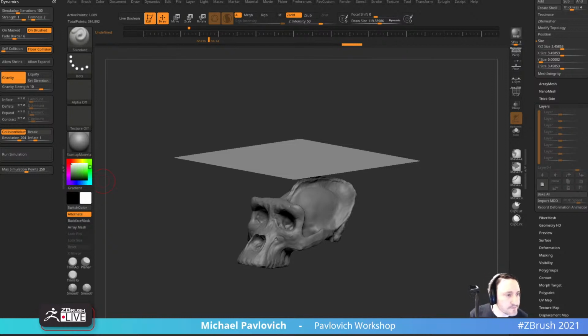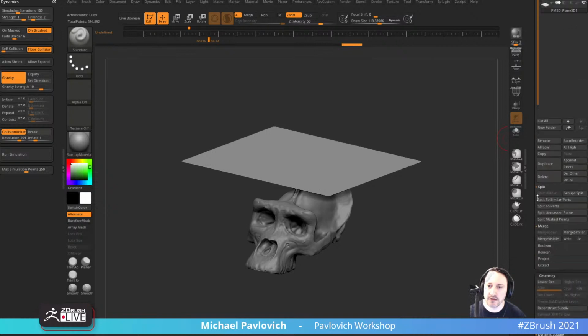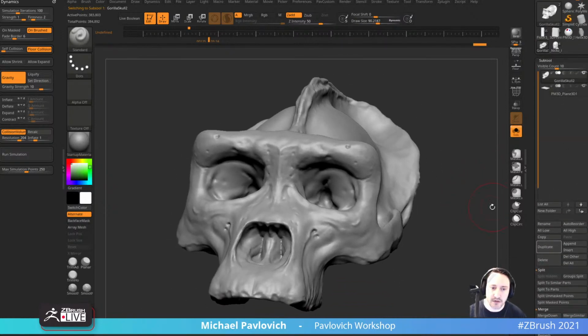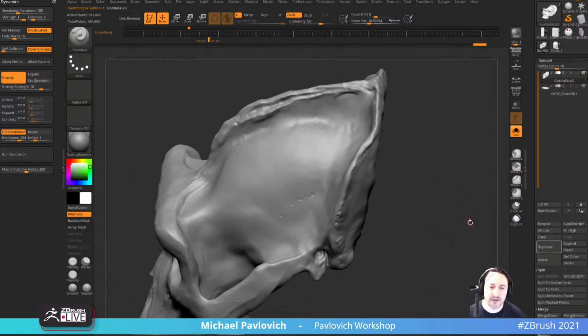Cool. Do you have to re-topologize your mesh for print? No. Usually just Decimation Master. Now you want to be careful with Decimation Master because if you have any kind of nasty geometry, if you have anything you need to clean up, like I'm sure there's some on here, but occasionally you'll have geometry that kind of flips and folds over itself.